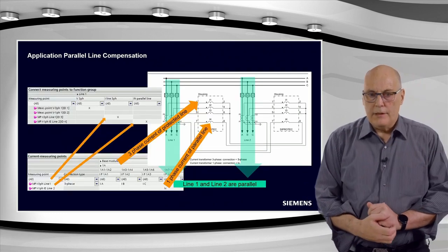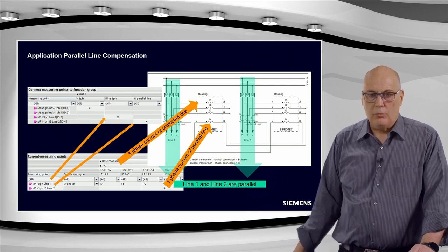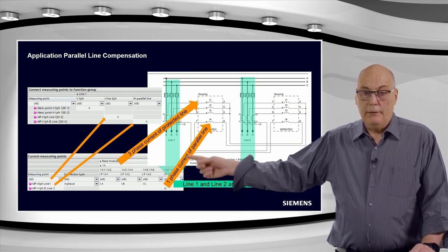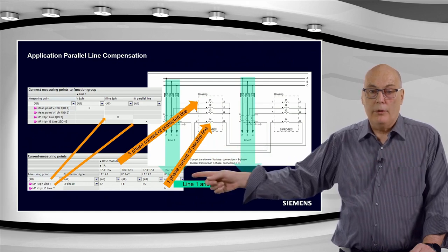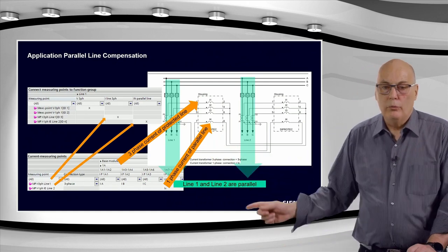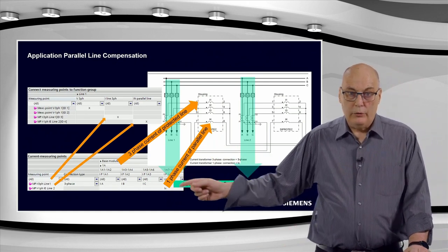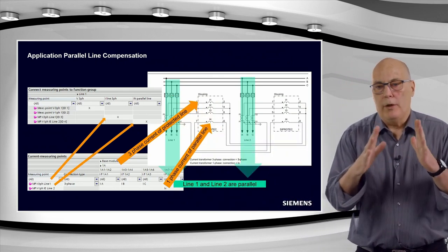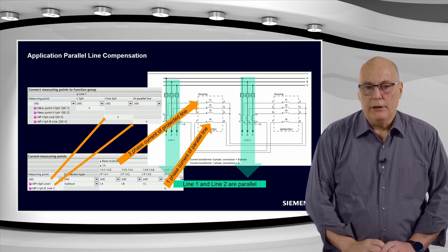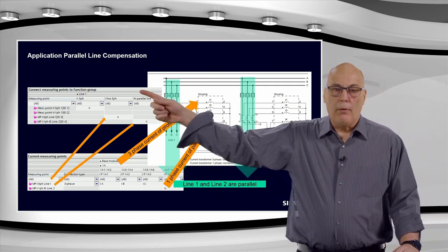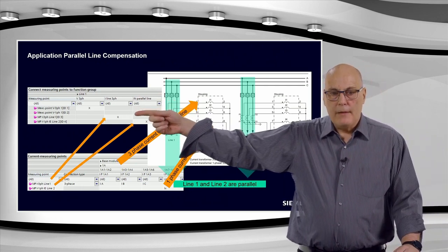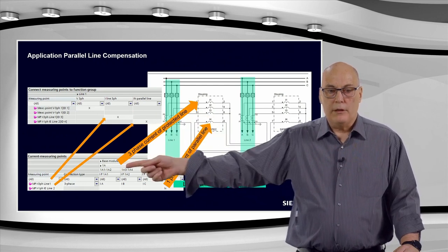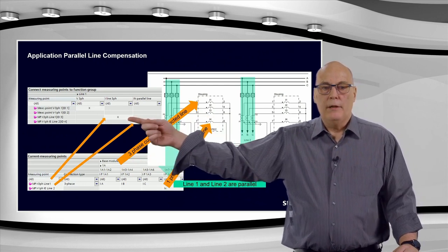Okay, that is the connection we did, and this is now just showing you how it was implemented in DIGSI. Remember, my parallel line current was the I4 current here. That was this one. I assigned that to that point over here. That was our measuring point routing we did early on, and now interesting here in the function group connection. Remember, we had the blue blocks, which were the function groups. You were connecting your function group line to the CT. Here, this is this CT over here, the top CT, the three-phase CT connected here.